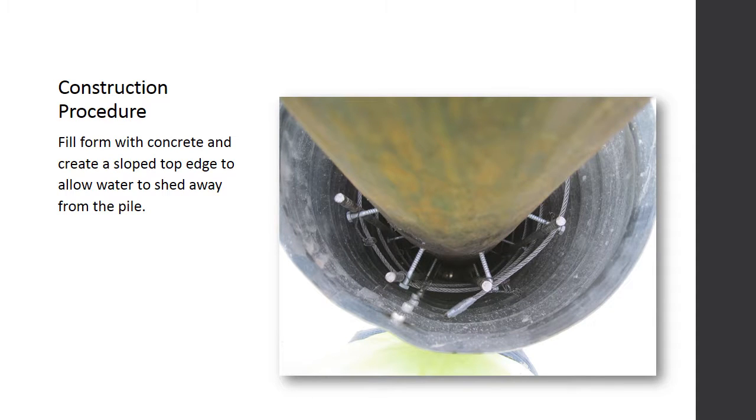To complete the repair, fill the form with concrete and create a sloped top edge to allow water to shed away from the pile.